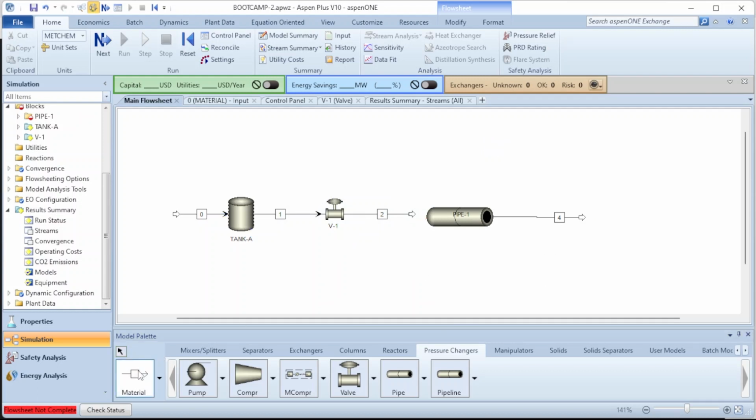So one way that you can deactivate an insertion mode, wherever it is, just right click. If you right click, it will just deactivate it. Or when you bring it, just use the escape button. When you use the escape button as well, it will also deactivate the insert mode. So now we reconnect, double click, then connect the feed stream.